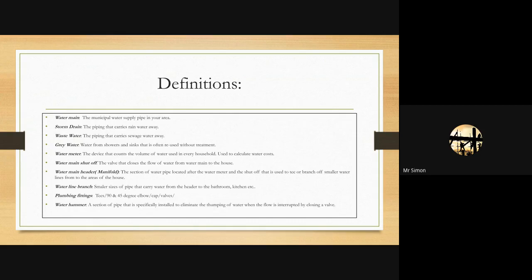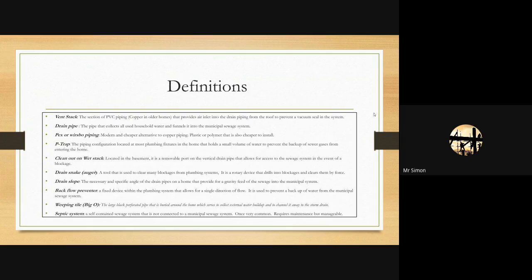A water hammer arrestor is a section of pipe that has air in it, and it's vertical, so it will never hold anything other than air. When the water wants to slam, it will actually push and compress that air. What it does is it stops the pipes from shaking and it just compresses the air. It acts as a cushion of air inside your piping system that relieves a lot of the pressure from that slamming. It's kind of interesting.